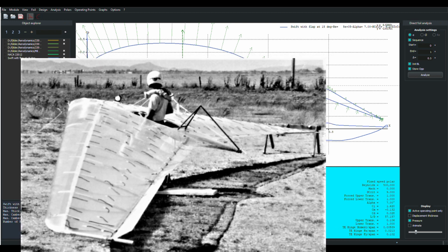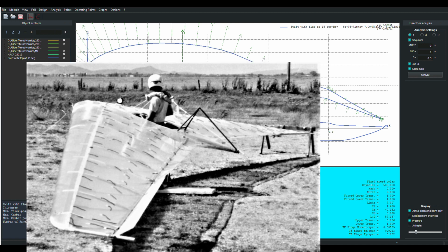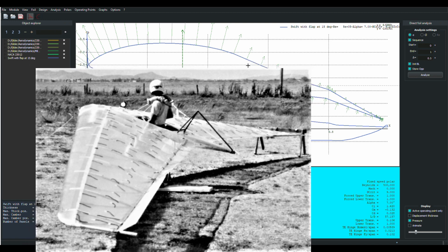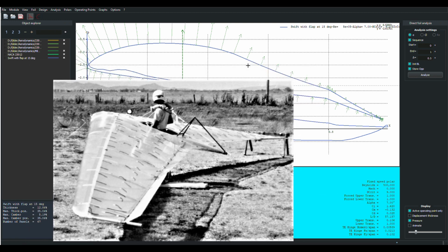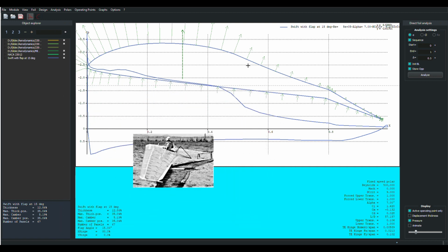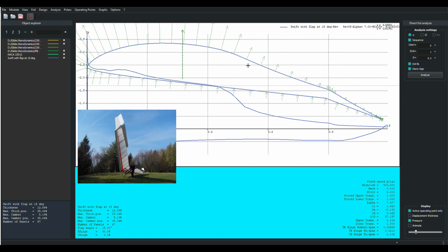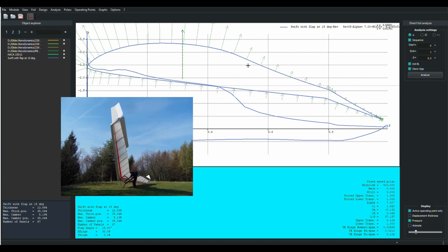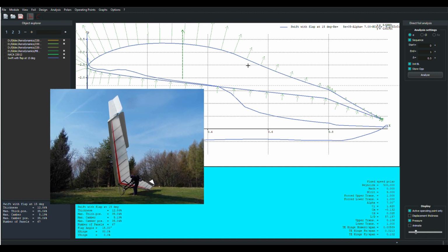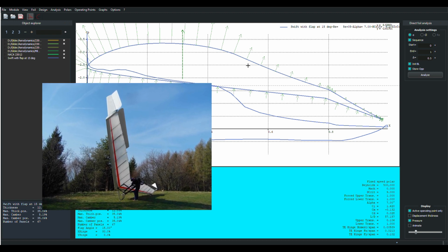So, kind of an interesting solution. Now it had a drawback. They were essentially strip elevons, which I've discussed way in the past, are bad in terms of the stall spin problem. So what I should have had on my original wing are essentially flat plate elevons that have a reverse taper to them. And where have we seen that before? Let me put up a picture of it here. It's the Millennium, designed by Steve Morris.